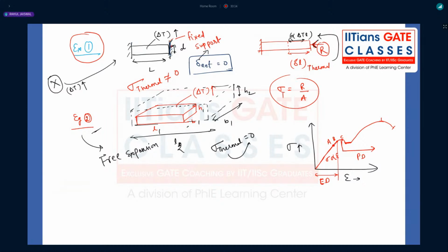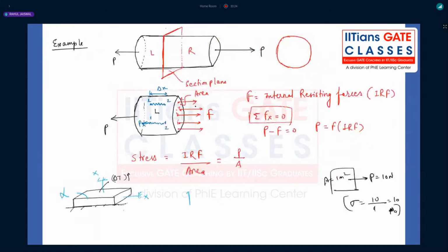because you can see that I am at a fixed position, I cannot move a little bit also. So you are opposing that move, basically the free motion of the particles. In earlier cases, the body wants to say we are at rest condition, we don't want to move, don't try to disturb the relative distance between the particles. But what you are actually doing is disturbing it, increasing the length between the particles. Then the particles will say, we cannot go like that, we will develop some internal resistant forces. Because of that, here the stress will be generated, right?